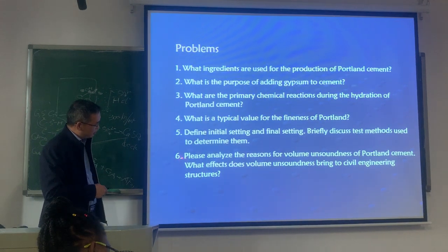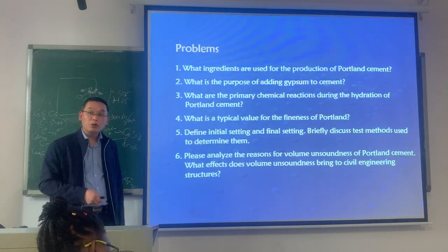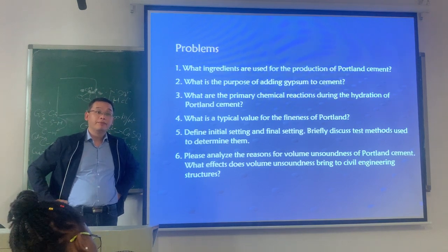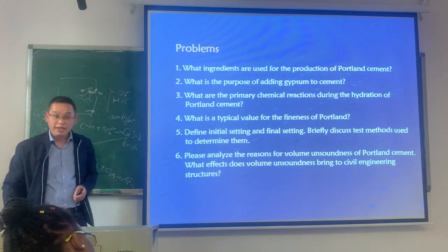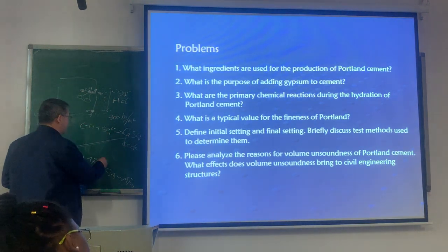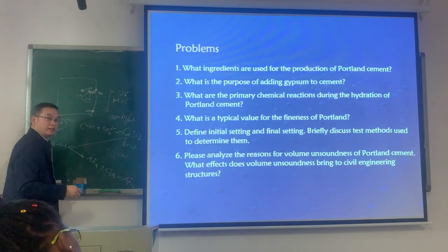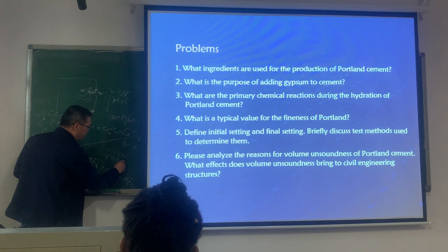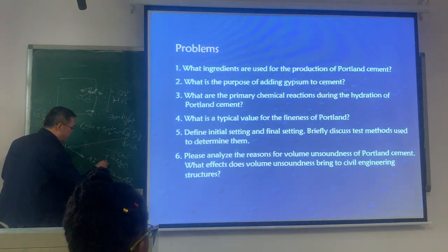And the sixth is please analyze the reason for volume soundness. What is the reason for the volume soundness? Three reasons. One is free calcium oxide. One is free magnesium oxide. Another one is gypsum.